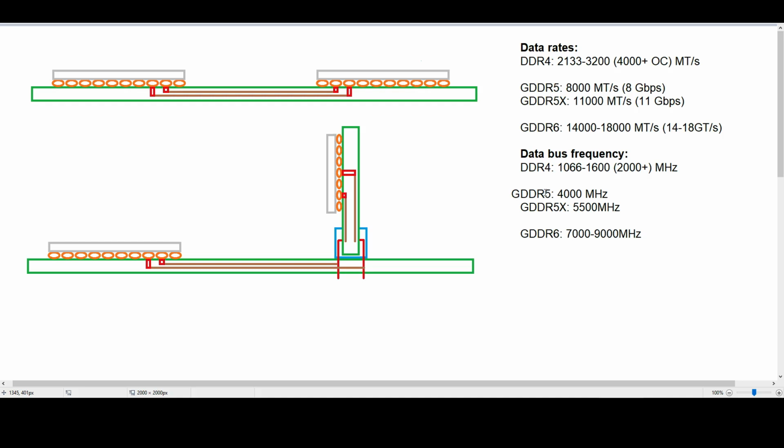If we change the shape of the pipe as well, so we go from a narrow pipe to a wide pipe, or then back to a narrow pipe, we're going to have a problem that there's going to be this large surface that's going to reflect the noise signal, the waves, back in a different way.